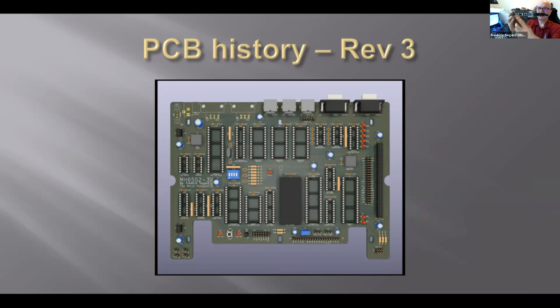All the ports, I have 2 serial ports, a third one actually which is TTL and not RS-232, and PS2 keyboard and mouse, and 2 NES controllers. And the reason why there's a specific shape to that PCB was because I wanted to put the buttons in the front of the casing, and they had to slot in at particular places, and there's a space also for the LCD.